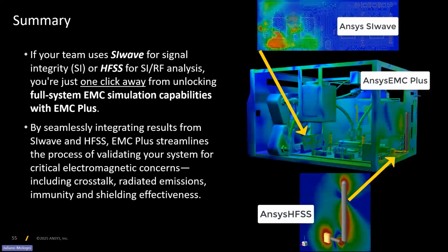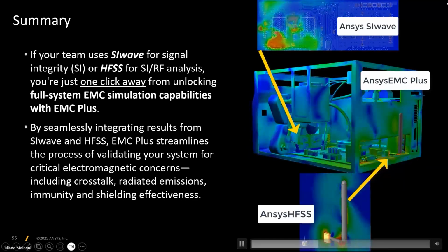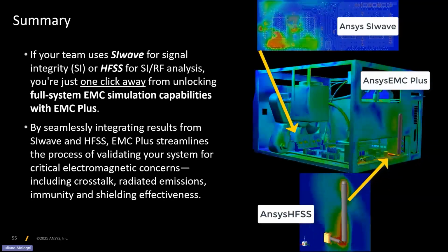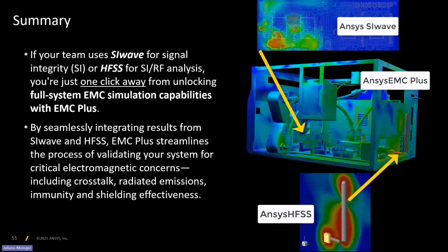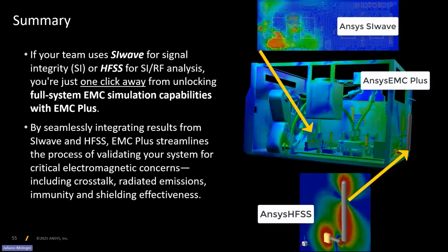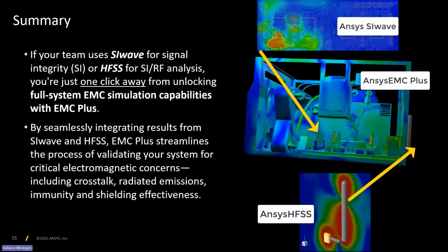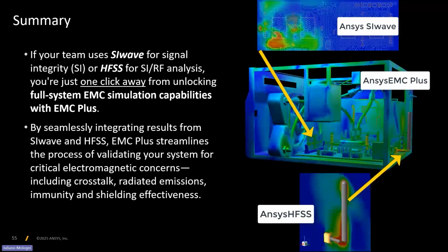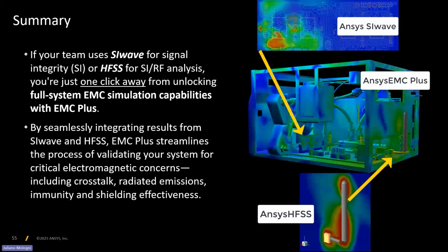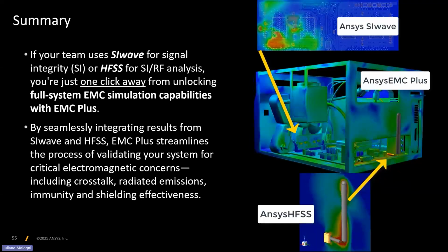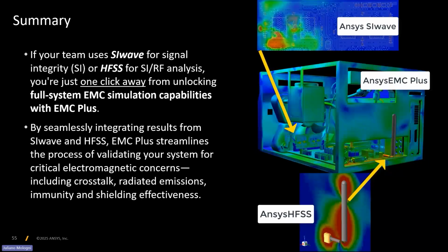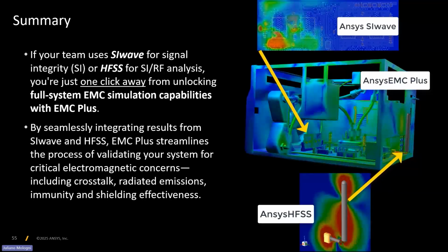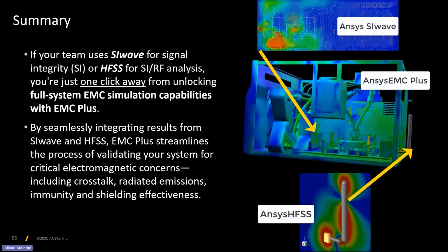The first question here is, can I use a custom rule set which goes beyond the rules listed in the EMI checker? Yeah, we do have an XML where you can change some of the rules, but if it's something that is extremely new, like if you want to compute the area that is overlapping a ground and the reference plane, a ground and a power plane, that might need some work on our side. So there's some flexibility, but if it's a rule that is brand new, then you're going to have to ask us to add that to the tool.